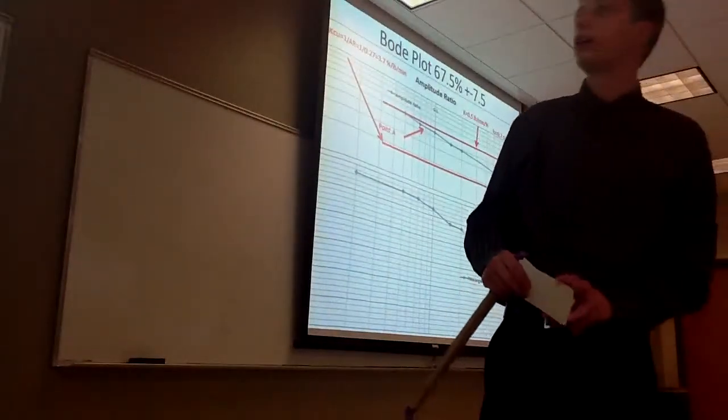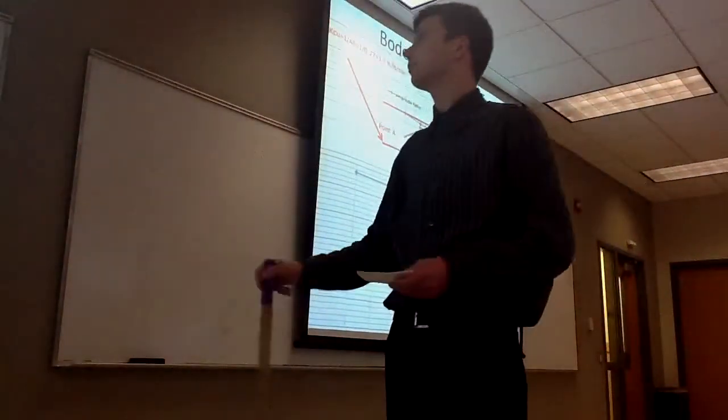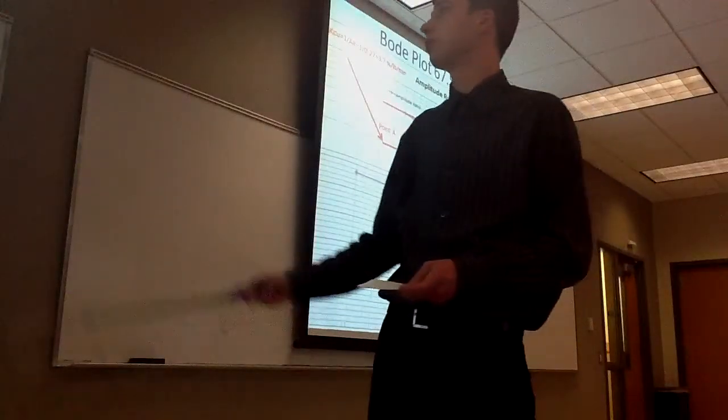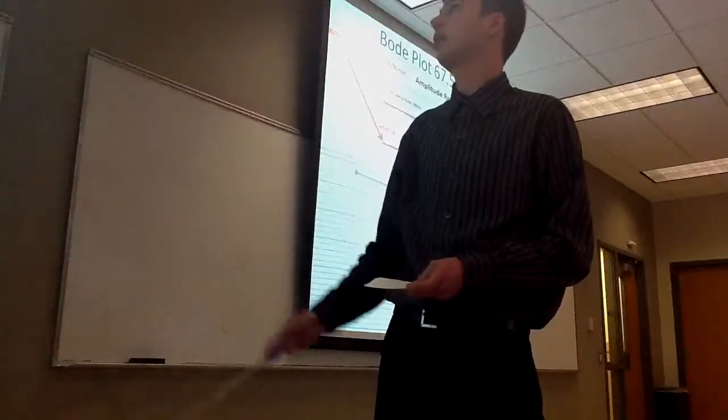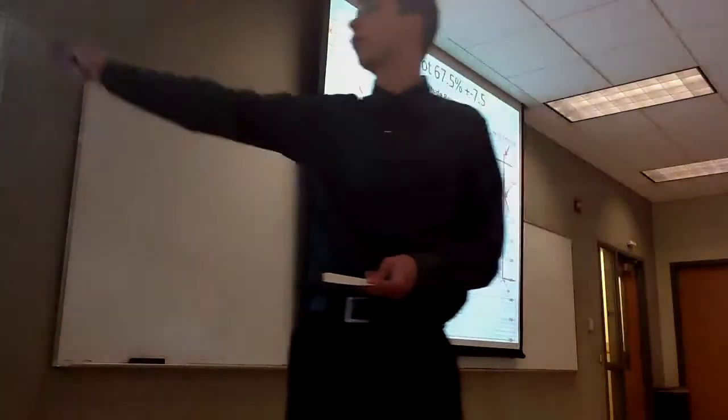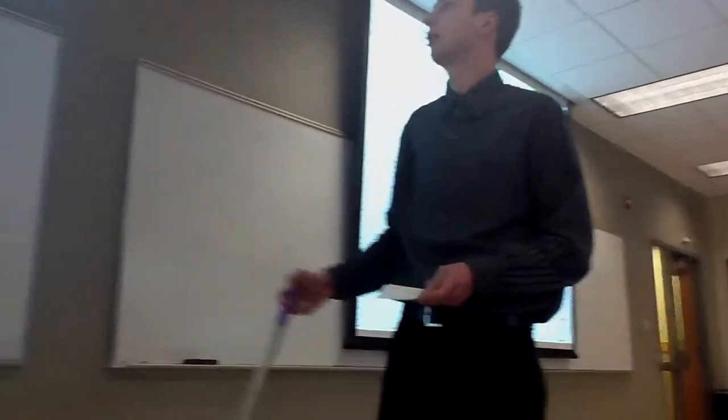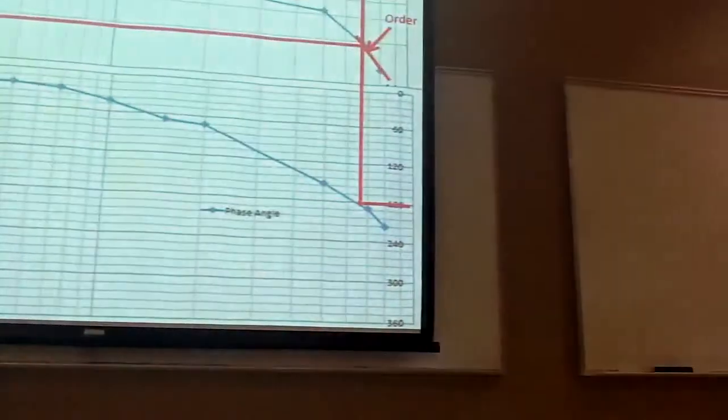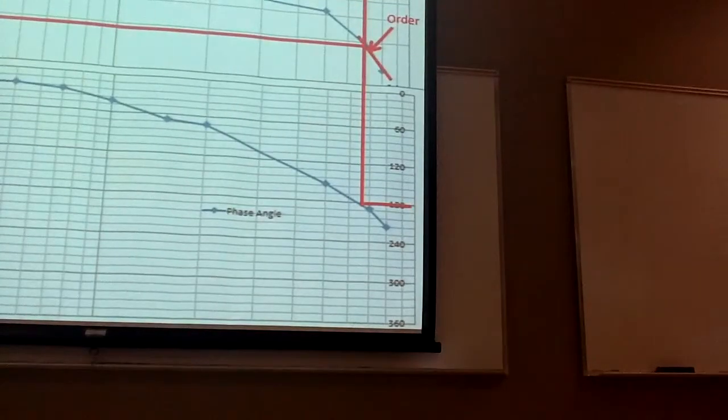This is our Bode plot of our middle range. The ultimate frequency was 0.7 cycles per second. Our gain was 0.5 pounds per minute per percent, and our KCU was 3.7% per pound per minute.